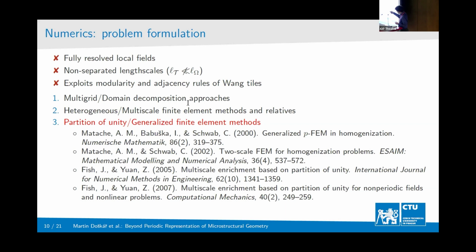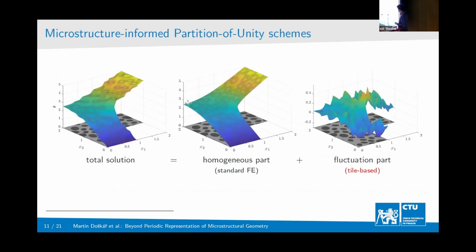But our first strategy was to use the partition of unity and generalized finite element method. And for that, we assume the split of the solution. So let's say this is a potential solution that we want to efficiently solve. And we split it into a homogeneous part using standard finite element with a finite element discretization that does not resolve any geometrical details.